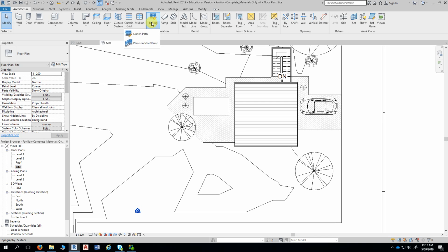Another tool that you can use to create a fence type, which you may not have thought about, is the curtain wall. A curtain wall can be adapted to reproduce a fence, for instance. A curtain wall essentially is a series of mullions and panels, and your common good neighbour fence is frame and panel. So I'm just throwing that out there, giving you some ideas on how you could produce fences, maybe using the curtain wall tool or as railings.